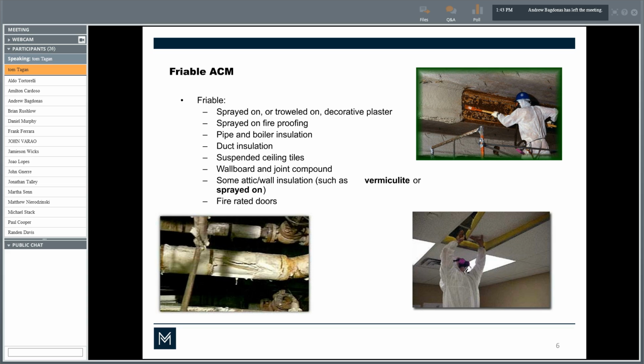And the concept is that because a lot of buildings have steel frames with concrete decking above, that steel frame helps to support that concrete floor. In the case of a fire, if that floor, the steel, is heated up to the point that it begins to melt or to deform, you have the potential for the concrete floor above it to collapse. This is what happened in the World Trade Towers, in that the steel buckled under the heat of all that jet fuel, and as that steel buckled, the concrete around it collapsed, creating the situation that occurred.